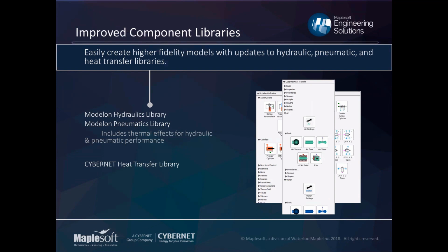We like to call this sort of coarse grain heat transfer effects, because while it doesn't offer the kind of granularity that, say, an FEA technique would, it does offer quite a lot of detail that you can use when you're in an earlier design phase, where it's still easy to pivot some design choices, to work on some countermeasures. Typically, if you're putting in all the resources into an FEA approach for heat transfer, you might be further along where it's going to be a lot more money and time to make some design modifications.